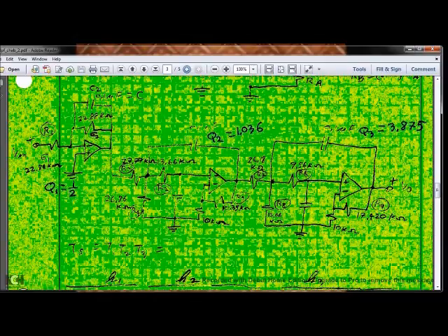The first element on the left is based on an operational amplifier. It's a first order section, an inverter. Our second cascade element is a biquad, a second order section. It's based on a single operational amplifier, and this is called the Sallen-Key configuration. We'll calculate the magnitudes of these resistors, and we'll set the capacitors to 0.1 microfarad. And this resistor right here, we'll set it at 10 kilohms. This is the third element in the cascade.